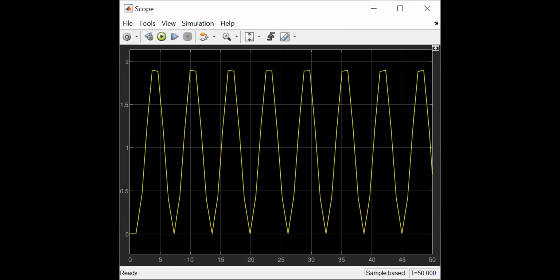Now, I want you to look at the right-hand corner where there is Auto ODE. What this means is, to solve this system, it's going to use ODE45, the MATLAB solver that we used in last class. Now, I want you to left click on Auto ODE. Here is the setting. It says View Solver Setting. Click on View Solver Setting. It will take you to the dialog box of the solver.